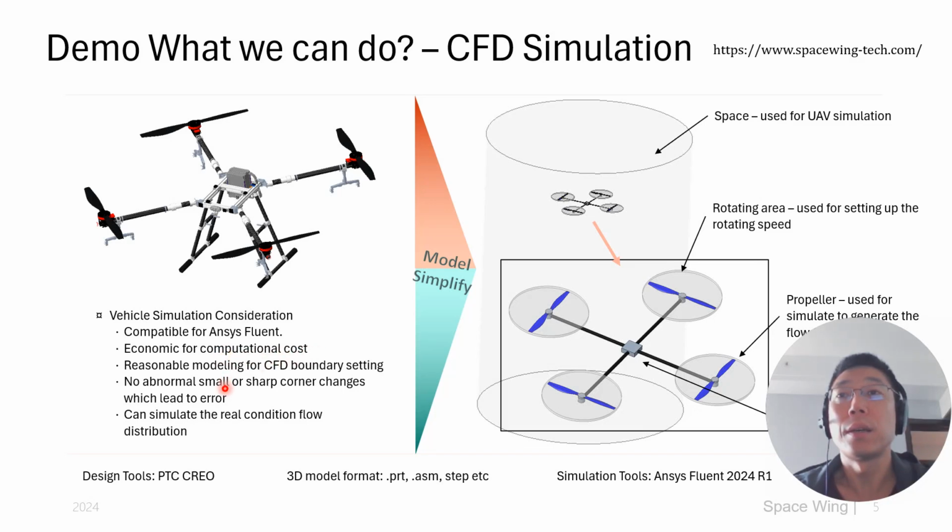It's also helpful to have reasonable modeling and boundary setting, so there will be no abnormal, small or sharp corners, which are very easy to lead to errors.